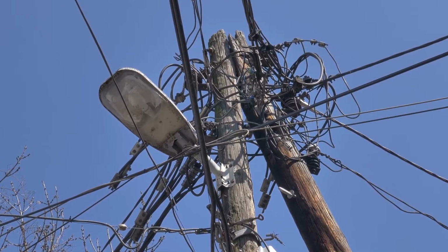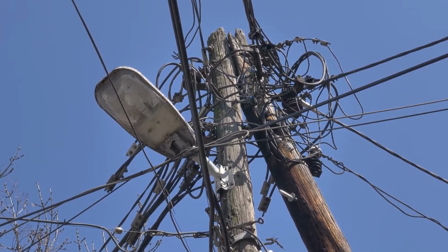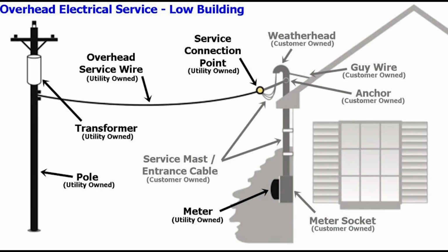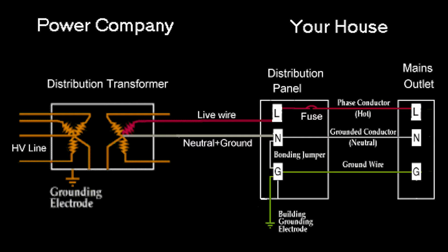Utilities use circuit breakers to de-energize and re-energize individual distribution circuits that are faulty or require maintenance. The distribution substations supply power to the primary distribution circuits called distribution feeders. The distribution feeders carry power from the distribution substations to reach customers. Overhead wires supported by utility poles are the most common means to support distribution feeders. Underground cables may also be used.